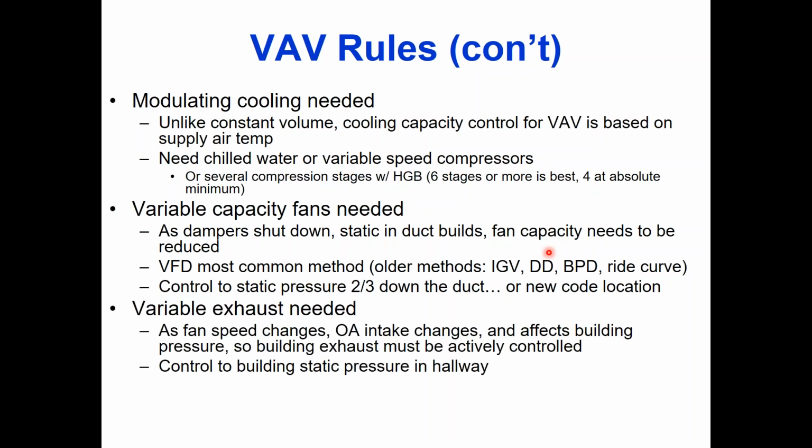And then if we're going to have variable fans, that means we're going to end up with variable outside air intakes, which means we need to have a variable exhaust system, either staged exhaust or variable speed, and we control it based on building pressure.